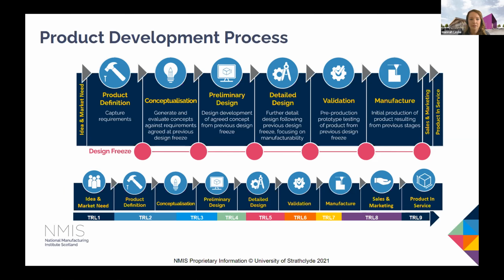and design. In preliminary design, the chosen concept goes through verification checks and initial verification to establish that the concept can perform the intended function and possibly optimize the geometry a little bit at this stage. This is where you'd also start your CAD modeling in earnest. In detailed design, the focus is on manufacturing and materials for the concept, moving it into a state where it can be manufactured through the production of general arrangement, GA drawings, and bills of material, and so on.